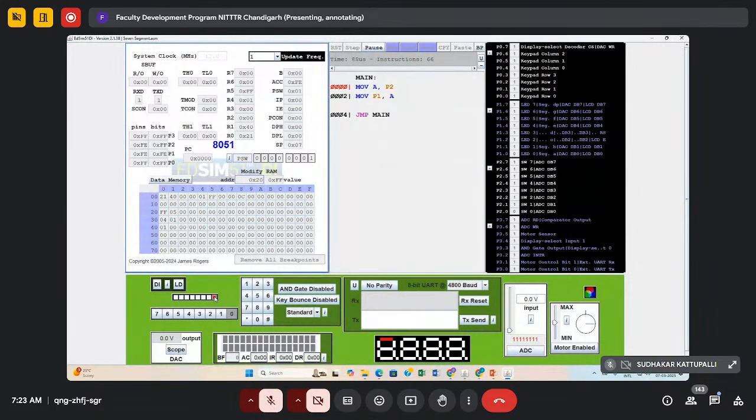So what we can also do is, same in the case of 7 segment. Suppose someone has pressed switch 1. The complicated thing we do, then I want to display 1 on 7 segment. Then you'll make it jump somewhere. You basically compare it with some number and then move to some subroutine. In that subroutine, you will make 7 segment display 1. So that can also be done. So whatever switch you press, the subsequent LED